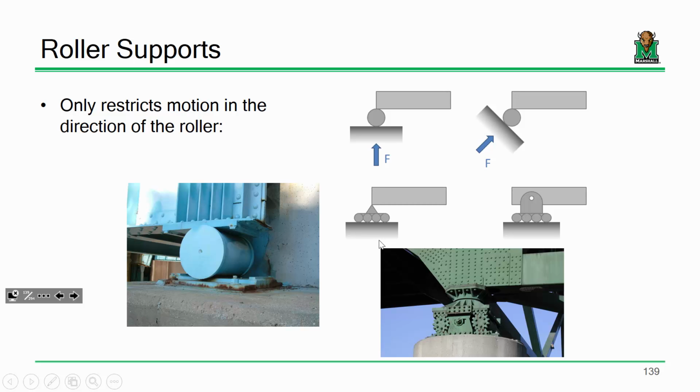So we affix one of the supports using an expansion bearing, which is basically saying we affix the girder to a sole plate, but we use slotted holes to allow it to translate a little bit. So the idea is that it's still being held up and down. It's not going to fall, but it's allowed to move a little bit. Does that make sense? A fixed bearing doesn't use slotted holes, it just uses a standard hole to keep it in place.